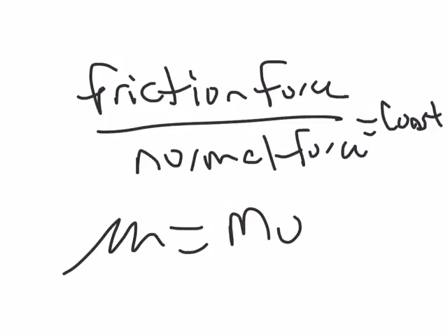So you can see in the graph up top, coefficient is really high on dry concrete, and then it gets much smaller as you look at ice. So smooth, clear ice, you can see the coefficient of friction is extremely, extremely small. So we want a higher coefficient of friction, and this is important when you're landing on ice or rain conditions.